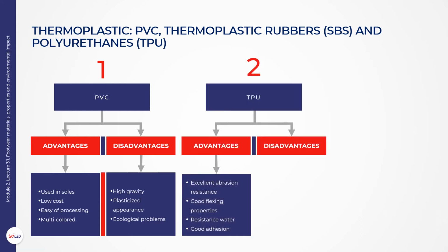Thermoplastic polyurethanes, TPU, have excellent abrasion resistance, good cut and scratch resistance, high tensile strength, excellent flexing properties, resistance to seawater and microbial attack and good low-temperature performance. In addition, TPU parts do not splinter, transparent formulations can be made with glossy and matte areas molded together, they have excellent adhesion to other materials in a shoe, and can be manufactured in combination with other materials, such as PU, EVA or vinyl rubber, as pieces of different density or various colors.